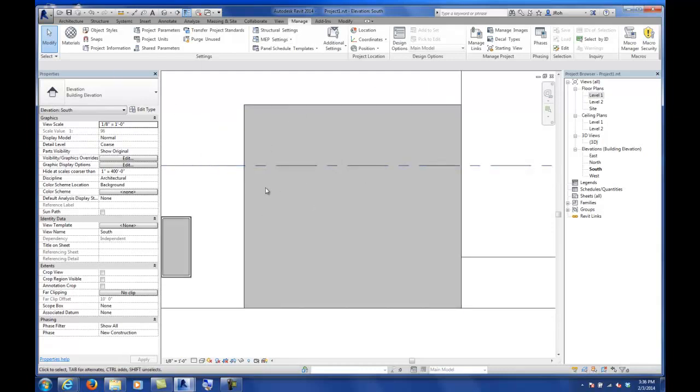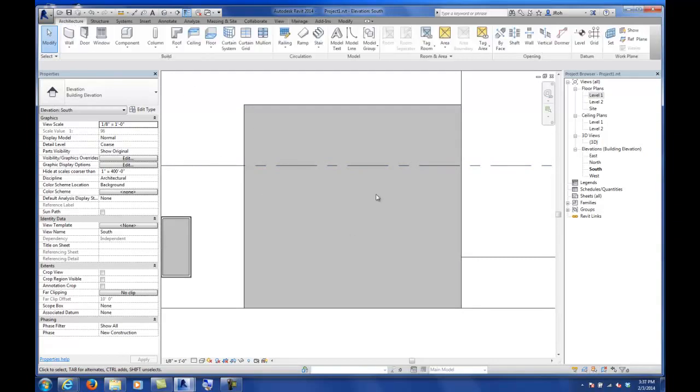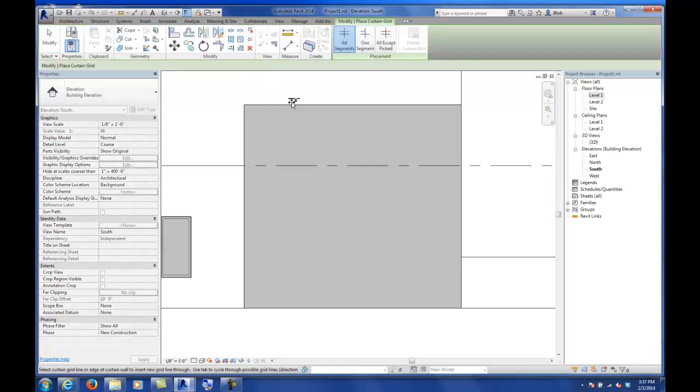So now while you're looking at this in elevation, what we can do is start to customize how this gets divided up in order for this to be our window wall. When we click on the architectural tab, you'll notice off to the top middle left, there's this option called curtain grid. Click on that and hover over your horizontal assembly or your horizontal line boundary of that glass, or if you hover over the vertical, you'll start to see that dashed line show up.